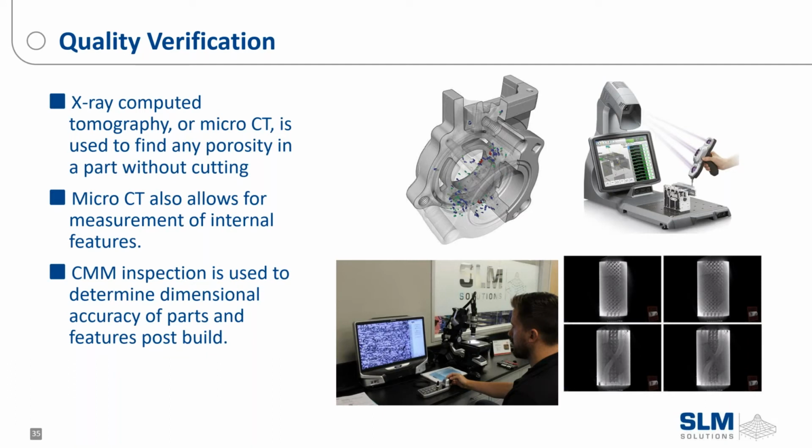You can see here on the right-hand side, there's the part on the top and bottom. On the far right, this part is made completely support-free. It is built, cut off the plate, and finished. There's no support required. The larger picture and the part in the middle here was designed and optimized. This is actually just a scale model of the part needed to be made, but there's a lot of support material inside that needs to be removed. And I can tell you from experience, because I was the one who cleaned this, it takes hours upon hours of cleaning and removing the support material.